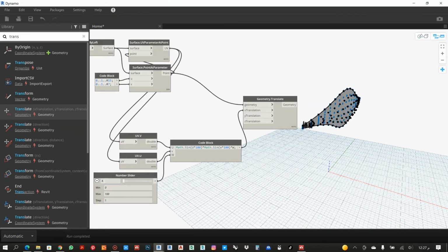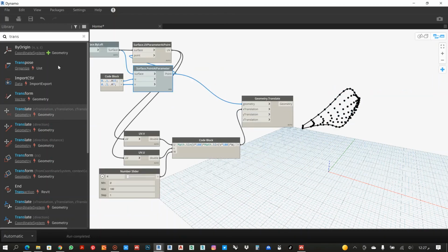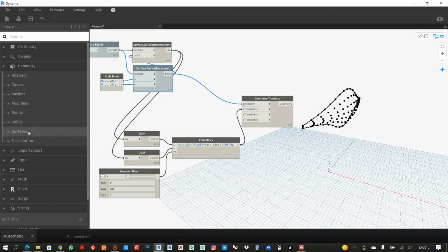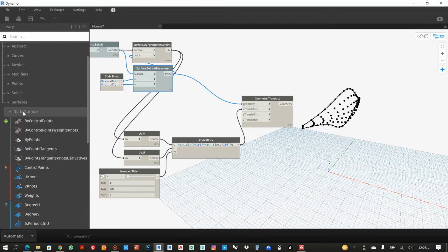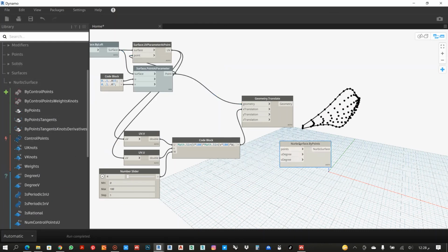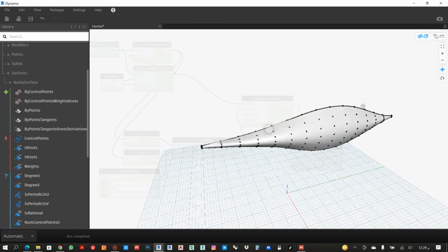And this value, if I increase it, for example, let's make 10, it will increase the height of this curve. Let's go back again to 4. And then let's stop the preview on this point, and from surface, I will make surface by points. If I choose these points, I can see now it makes for me the curved surface, the same as the concept that we need.